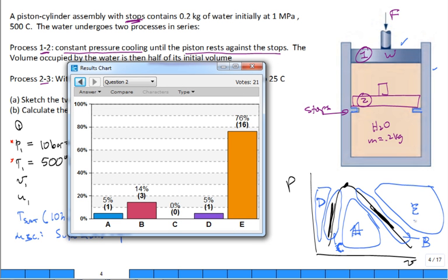That's where the superheated vapor is. What is B? Saturated vapor. What is A? Two-phase liquid vapor. What is C? Saturated liquid. What is D? Compressed liquid or subcooled liquid? Your choice on the terms. All right, so there we go, right?